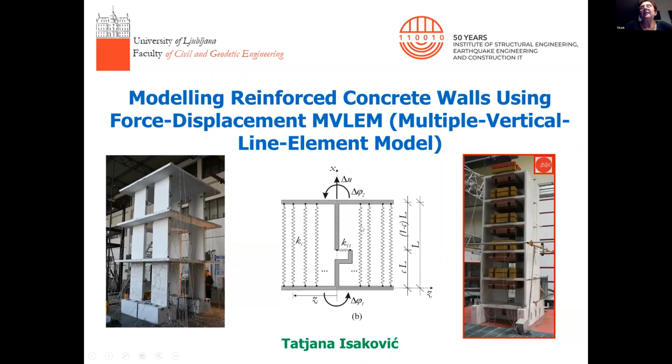As already introduced, I'm going to talk about the multiple vertical line element model for reinforced concrete walls, developed at the University of Ljubljana. It is not the element already included in OpenSees, but a different kind of element, and it is available in the local versions of OpenSees in Ljubljana.